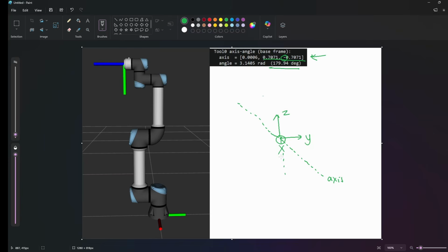If we have a positive rotation of 180, it's basically like saying I'm mirroring this y-axis here. If I mirror this, let me just use a different color, then the new y is going to be pointing down. And the z, if I mirror across here, will point this way because it's being mirrored across this axis. And the x-axis, if you mirror it about that axis, is going to flip so it goes inside the page. So this is our new set of axes here.